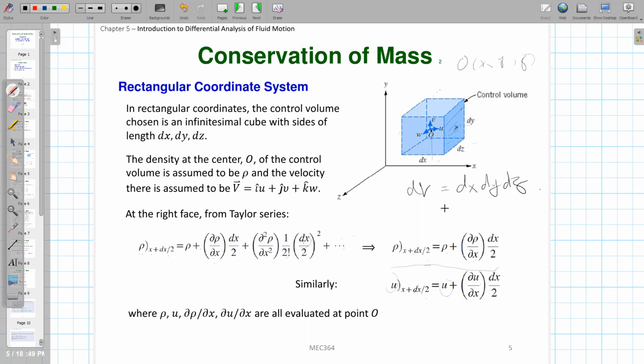And this u we define as the positive x direction, so u will be going in the positive x direction, and this surface area is also in the positive x direction, so you will have a positive sign for it. When you do v dot dA, because this is the mass flux, you will have a positive value. So it is just rho times u times the area, and the area is dy times dz for this surface.